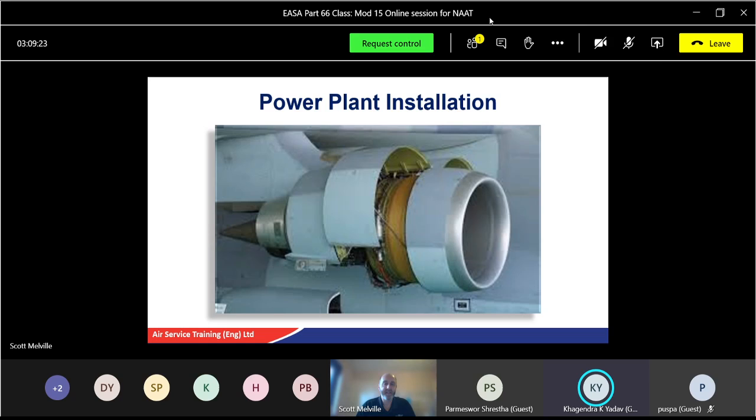If it's up, the valve is closed. So if the valve is closed, what's happening to servo pressure? Pump pressure increase. Yeah, good. Servo pressure is increasing. So with servo pressure increasing, what's happened to pump output? Pump pressure also increasing. That's it, nice and easy. Whatever servo pressure is doing, the pump is also doing, like for like.